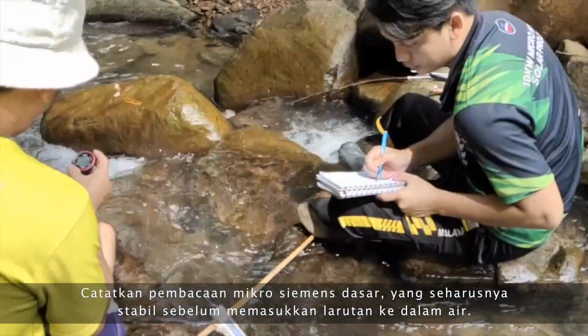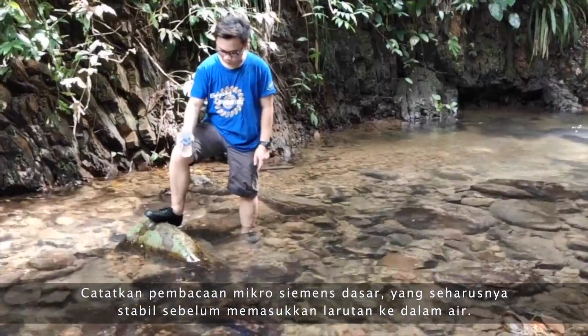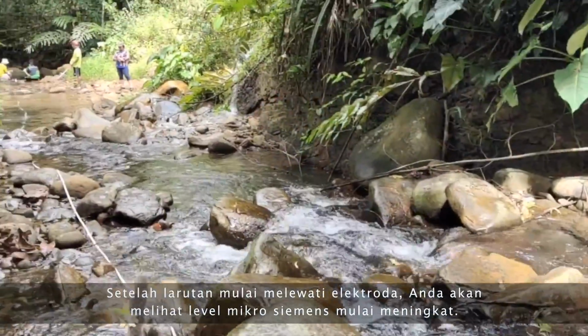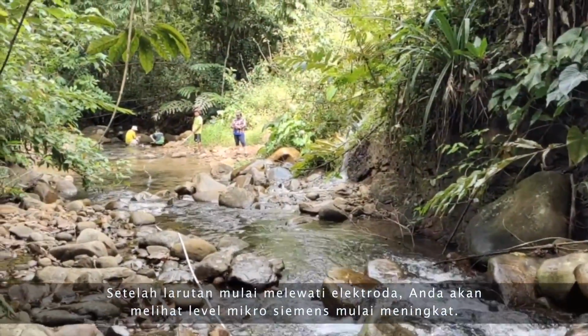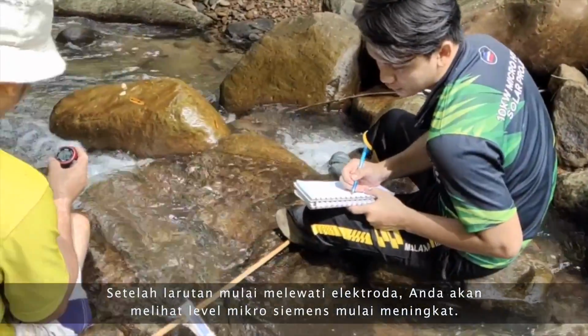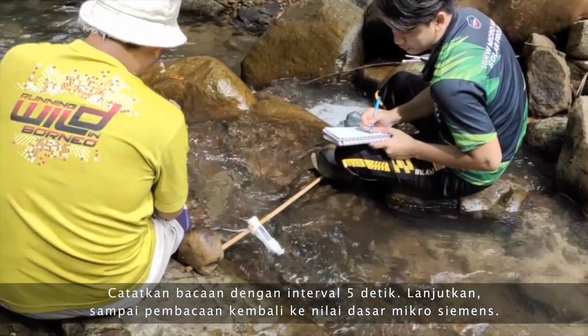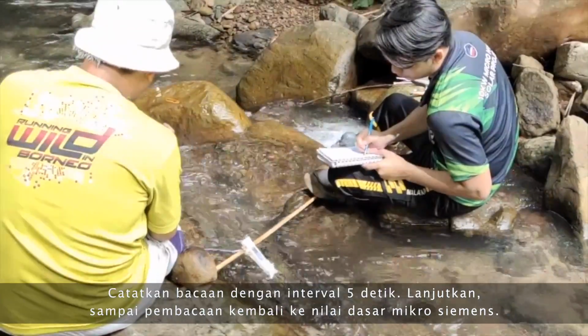Record the base microsiemens reading, which should be relatively stable, before placing the solution into the water. Once the solution begins passing through the electrodes, you will notice the microsiemens value start to increase. Take note and record the readings at 5-second intervals. Continue until the reading comes back to the base microsiemens value.